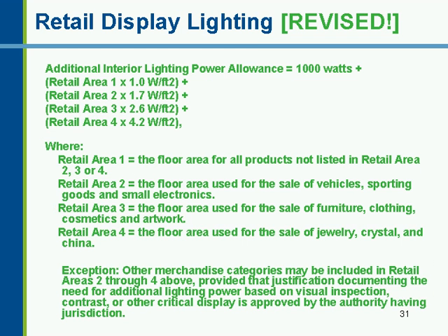And this has been totally revised, actually replaced, for the 2007 version. Some of you may be familiar with the 2004 provisions that provided 2 additional lighting power levels. They were hard to apply because it was hard to define when you needed either and how to calculate display areas, etc. So this has now been completely revised.